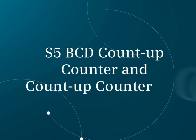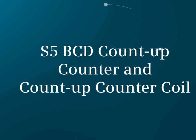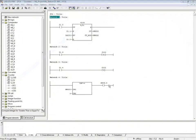In this video, you'll see the S7 BCD count-up counter and count-up counter coil. Network 1 has the count-up counter, Network 2 has the count-up counter coil, and Network 3 has a reset for the counter coil. The counter's name, C100, also acts as a coil and can be evaluated as a contact. This only tells, though, if the counter is in use or not.